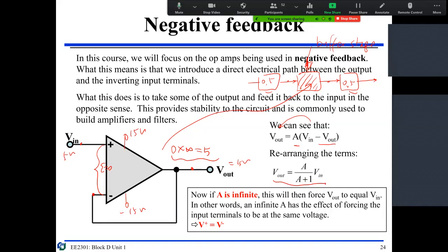If directly connected, it is not 0.25, it's 0.20, remember? That's why op-amp is so useful in practice. You insert an op-amp, you don't need to worry about impedance matching anymore. So this is called a voltage follower, or a buffer stage, to remove potential impedance matching issues.